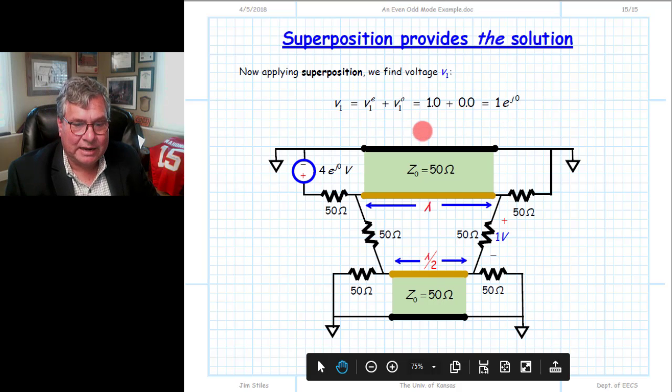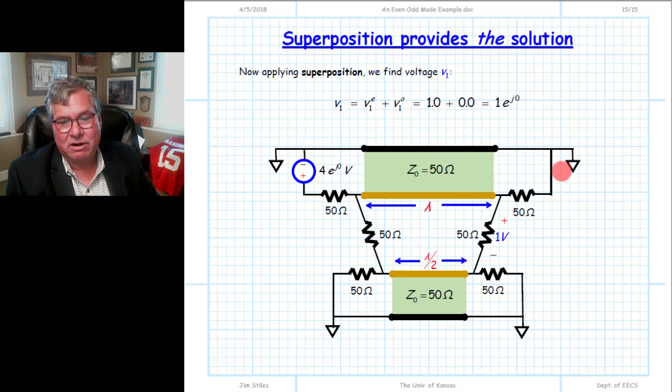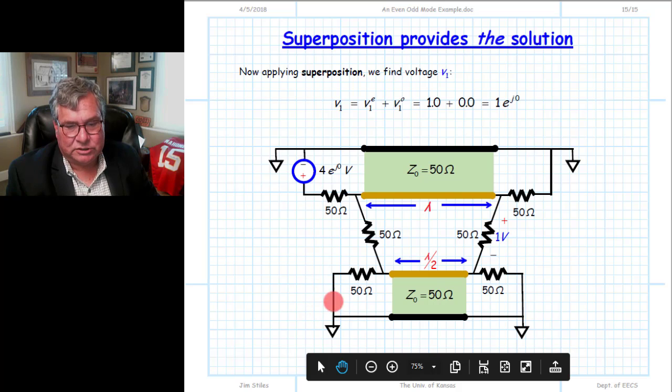The key thing is recognizing where the plane of bilateral symmetry is and how the source reflects to the other side. This source reflected over here, so this short circuit we needed to rewrite in terms of an odd and even mode voltage source. Again, there were no voltage sources on either side here. If we reflect across the plane, they are not affected. The symmetry is not disturbed.